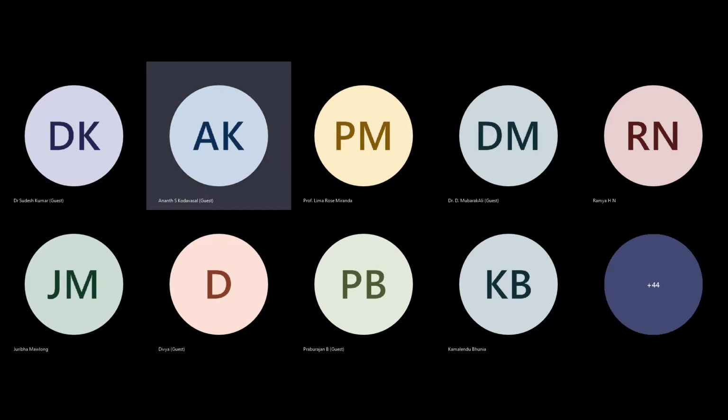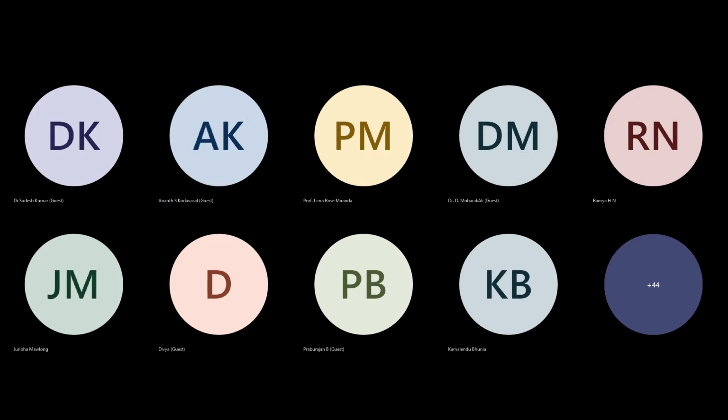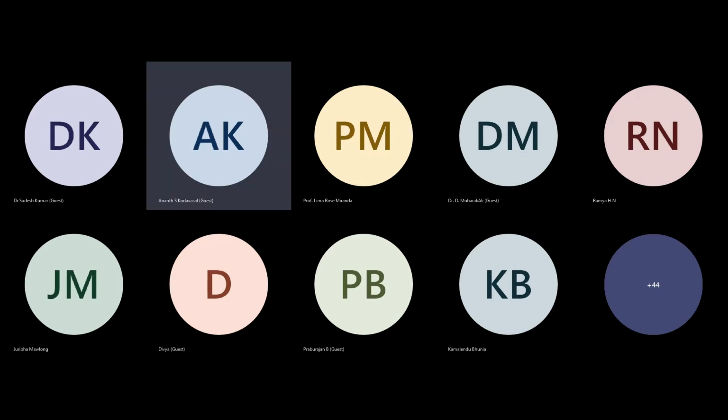The bisulfite directly goes to reduce the chromium, and hexavalent chromium becomes trivalent chromium, and when you remove it, you have to do the treatability study again and determine what will be the dosages required. And we carry it out at 2 to 3 pH. At low pH, we do the reduction of the hexavalent chromium.